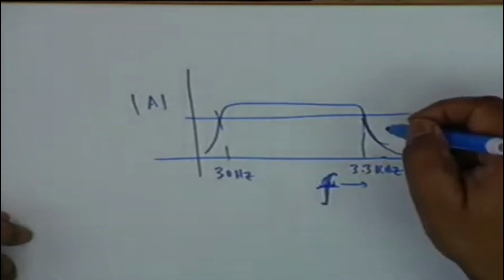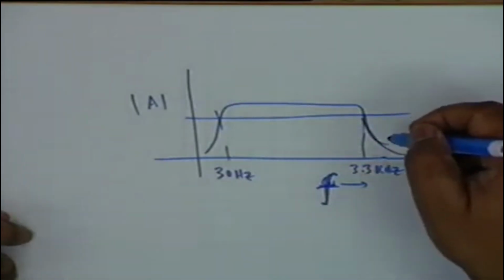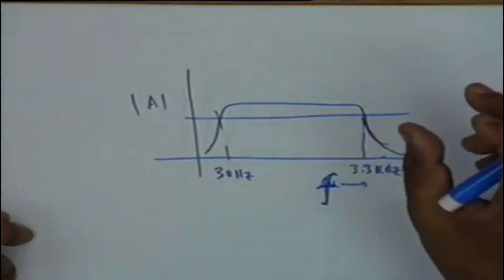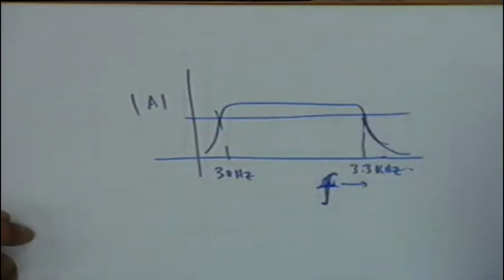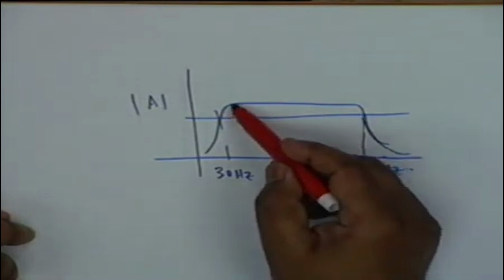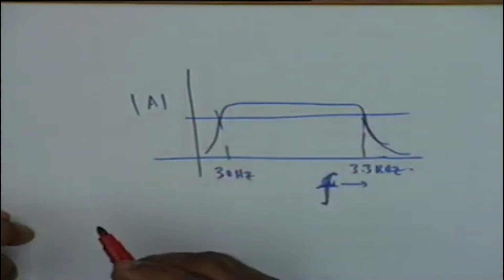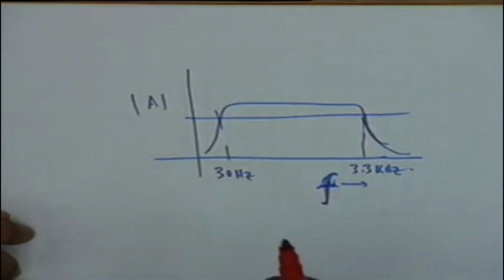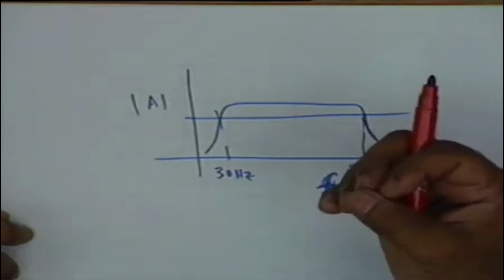All right, this is like decreasing the treble. In a stereo set you have two controls, one is a bass control, the other is a treble control. Bass control means you either increase or decrease the low frequency 3 dB point. If you increase the bass, the drums will come better, the tabla sound for example.